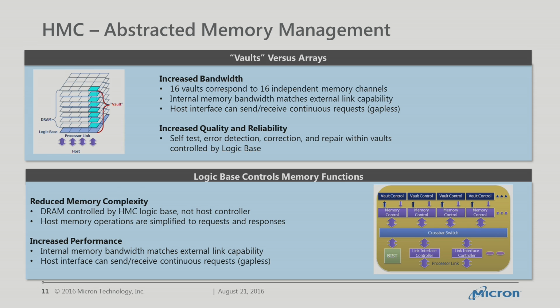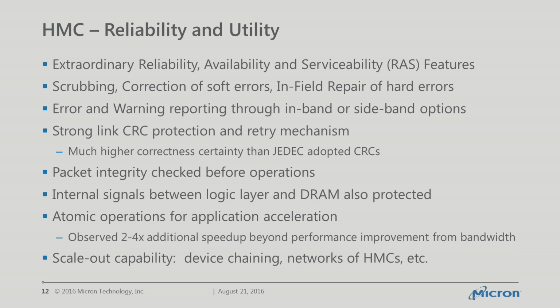And then internally, there's phenomenal processing going on, and I mean bit processing as in self-test. So the part actually in the field will self-heal. It has a memory tester on chip. It will discover errors. The ECC will carry you through that error discovery, and then we investigate and say, oh, that's a hard fail, and then we kill the bit and we dial in other resources, so now you don't consume your ECC to take care of those errors. So it's wildly more sophisticated than anything that came before it.